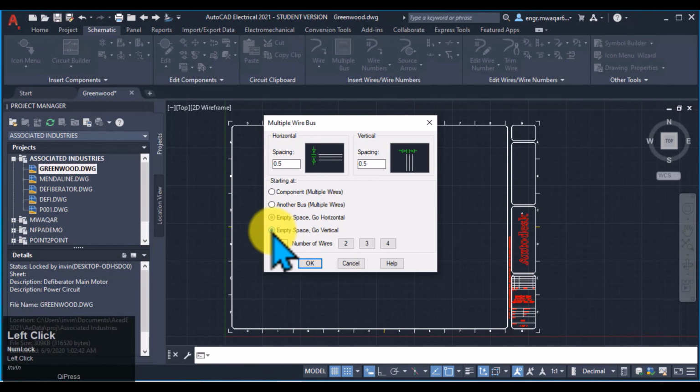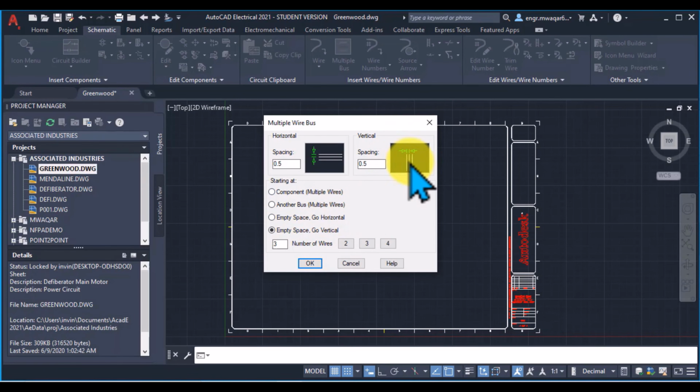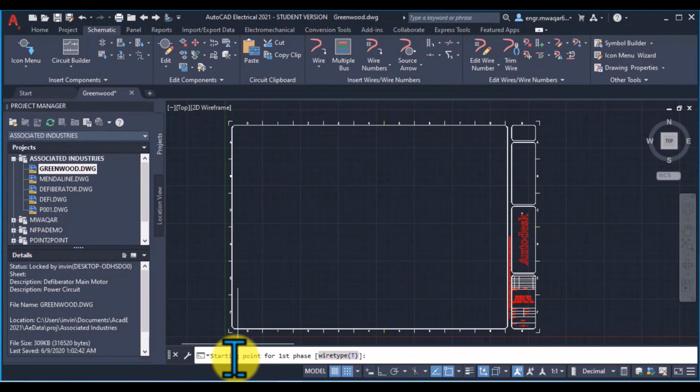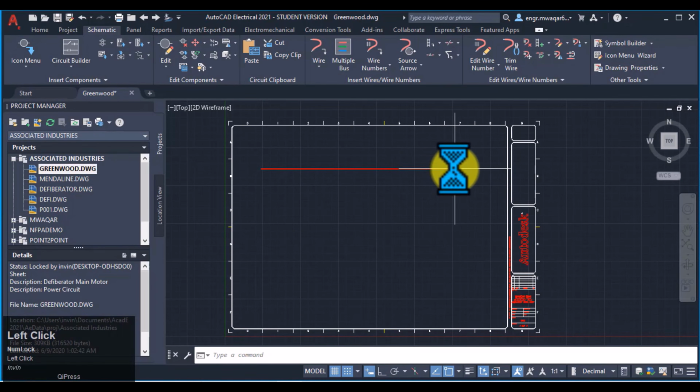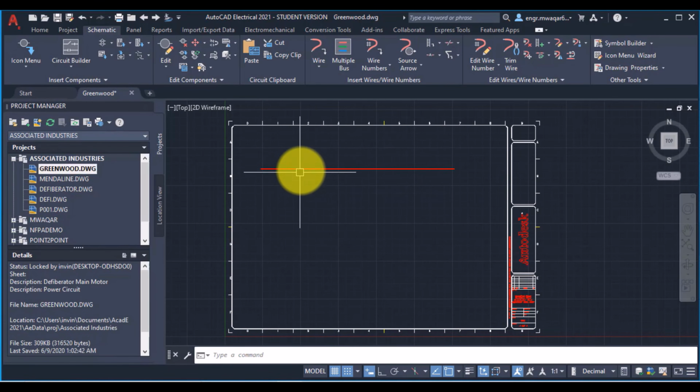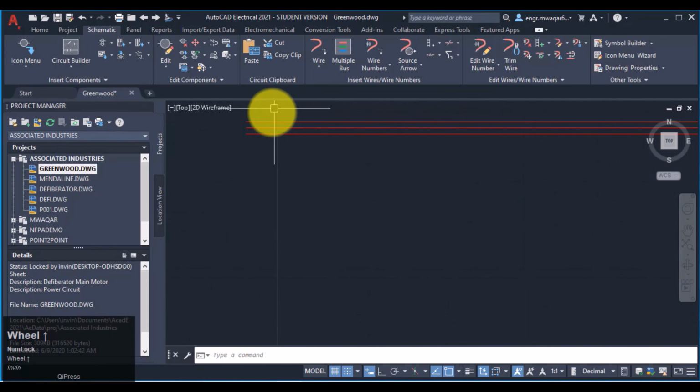Okay, let's move to the payoff. We've talked about the how: trap distances, X data, those tiny wires. But why do we go through all this trouble? It's all for the reports. The drawing is pretty, but the manufacturing floor runs on the reports, specifically the from-to list. The Suntech and Hagerman sources both emphasize this heavily. If you've done your job right, you can press a button and get a list that says wire 101 goes from relay 1, pin 4 to terminal block 2, pin 1.